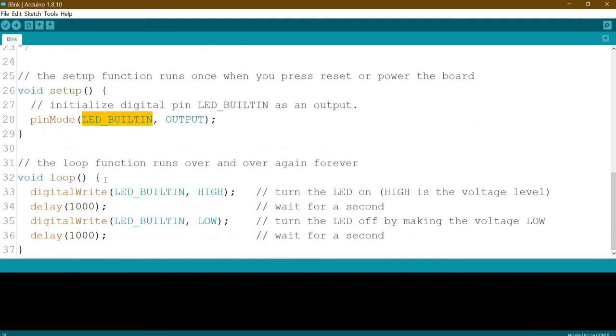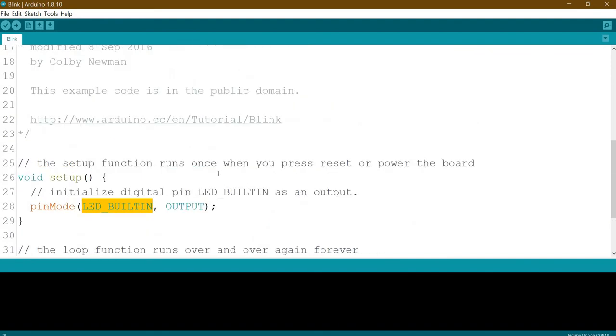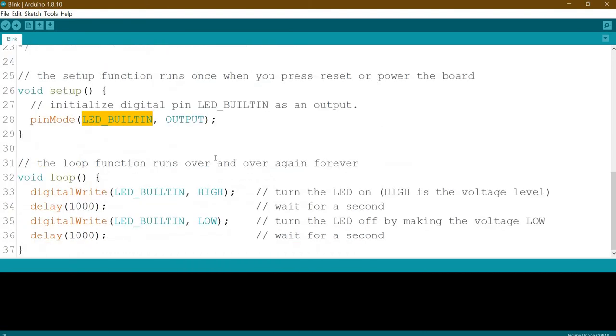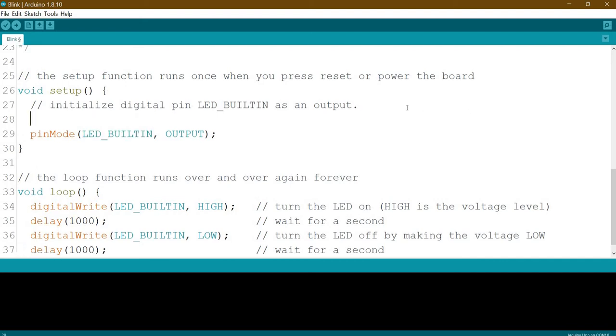By doing this, we can get some feedback from our code and from our actual setup in the Arduino MCU, which is the Atmega. Okay, so let's get started. First I will initialize the serial monitor here, Serial.begin, and define the baud rate, let's say 9600.